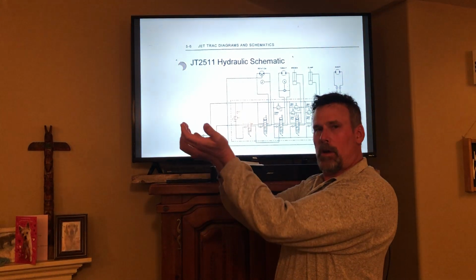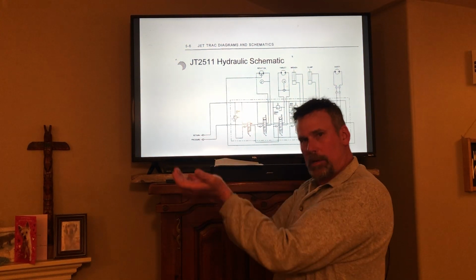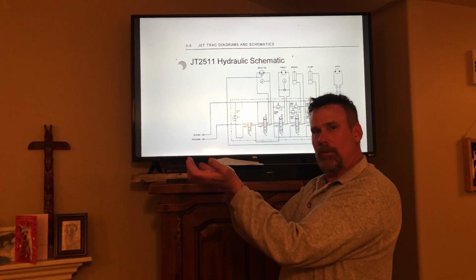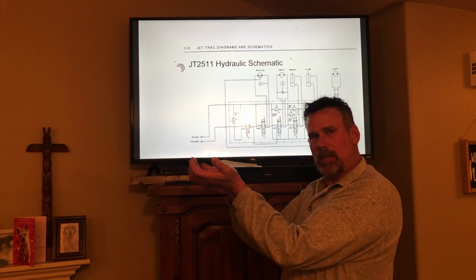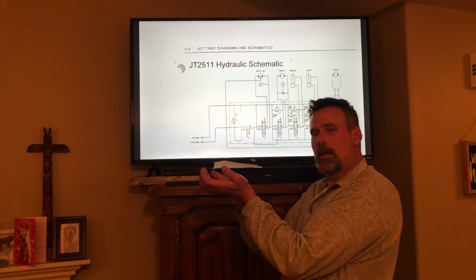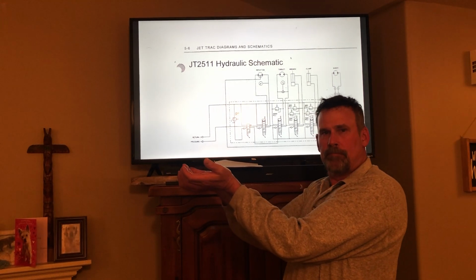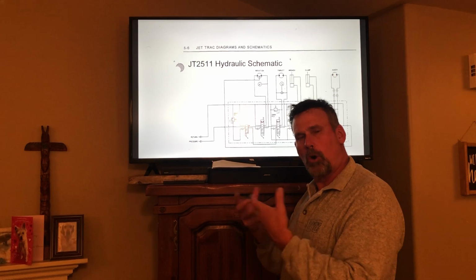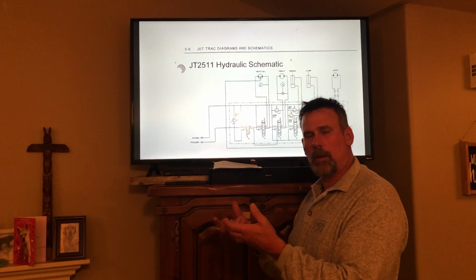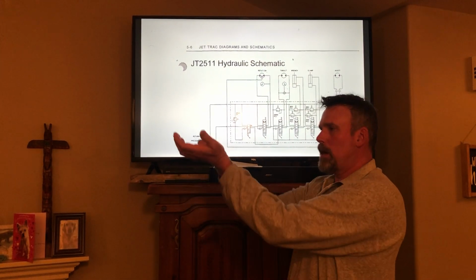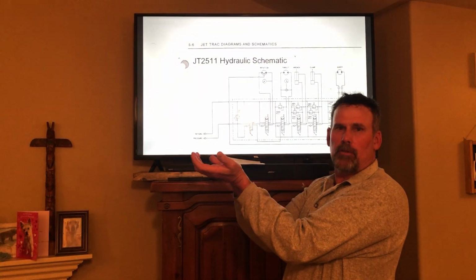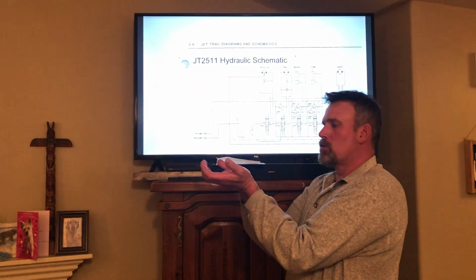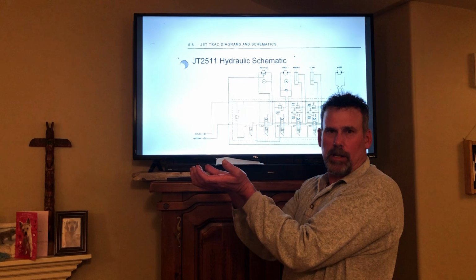And now work port A and work port B are both blocked, so that load of gravel, that bucket full of gravel, stays up in the air. Okay? And I drive over to the truck. All right? So it's taking a certain amount of pressure to hold that bucket full of gravel up in the air. Let's say it's taking 2,000 psi to hold that gravel up in the air. All right? So I drive over to where the dump truck is.